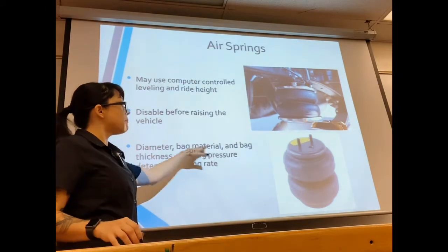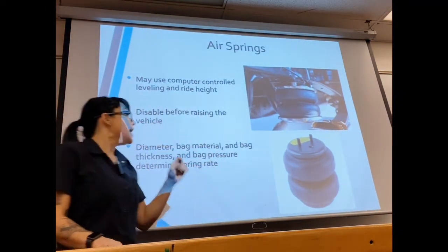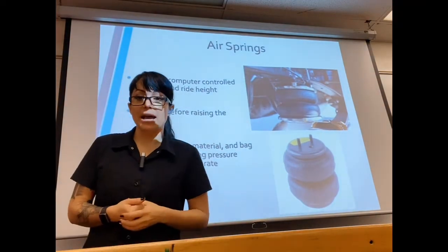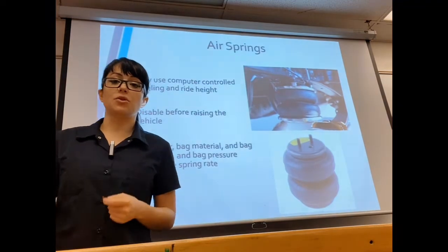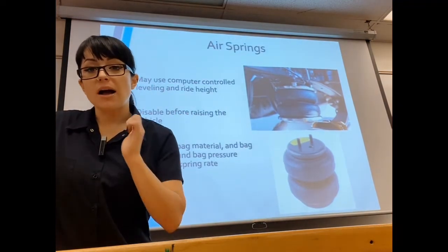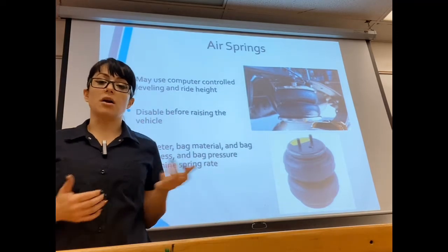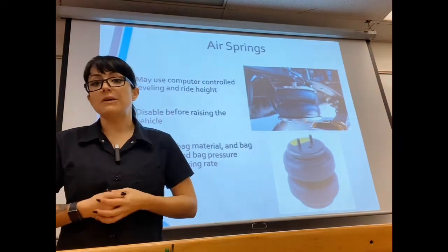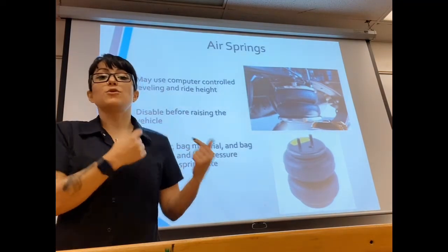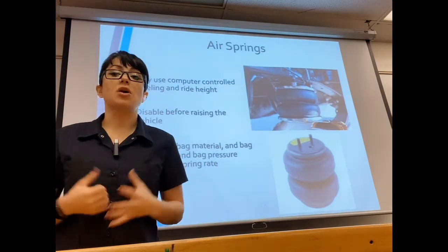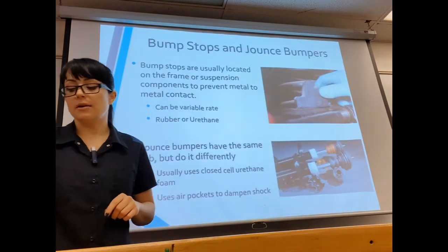Now, the diameter of the bag itself and the bag thickness, or the thickness of that material, is going to determine your spring rate as well. So if you're looking at a set of aftermarket bags, that's something to look into. However, aftermarket-wise, a lot of people will put airbags on and they will remove the shock absorbers and not put them back on. I always recommend you're going to need to make new mounts for shock absorbers because these are springs. They're not springs and shock absorbers, and so they don't do the job of a shock absorber, and we'll talk about that in a little bit here.